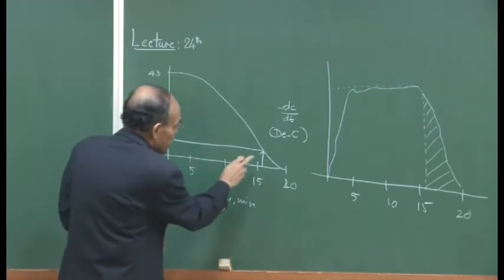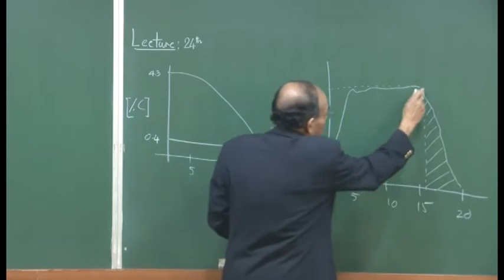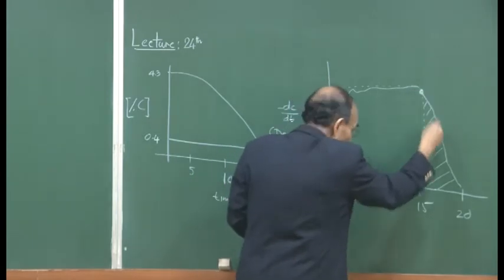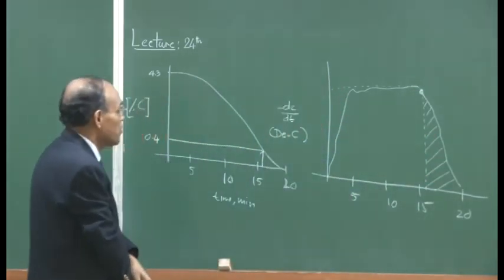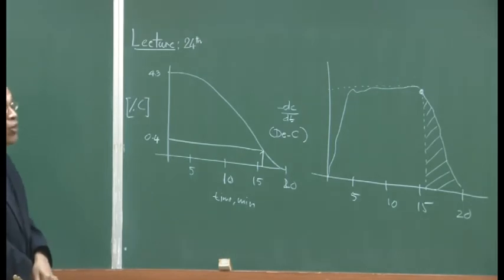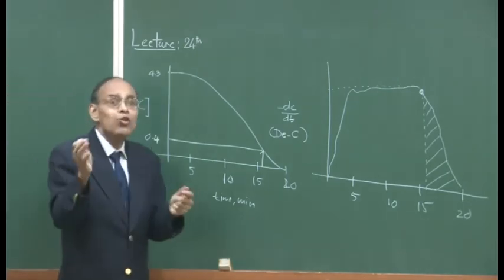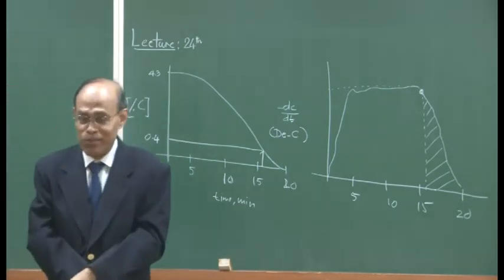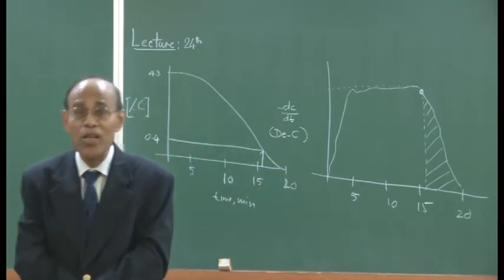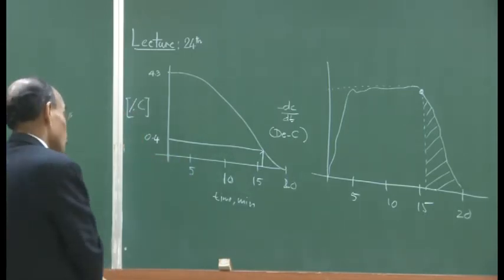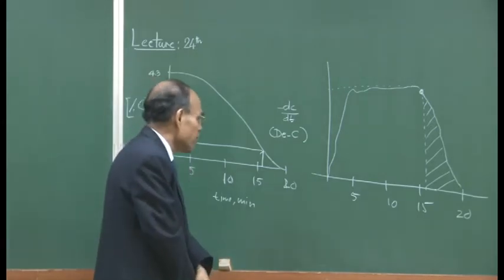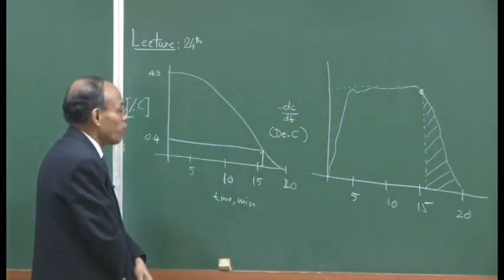So, your ability to predict from this point onwards the characteristic nature of the curve is very, very important in order to control endpoint, because you will be making diverse grades of steel in the plant. You are not always going to make 0.01 carbon, you may make 0.1 carbon, you may make 0.12 carbon, you may make 0.17 carbon, and so on and so forth.